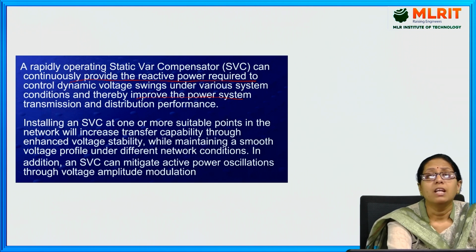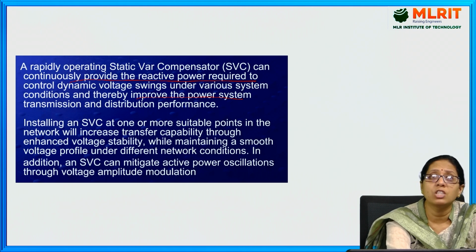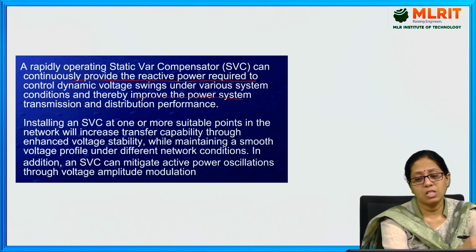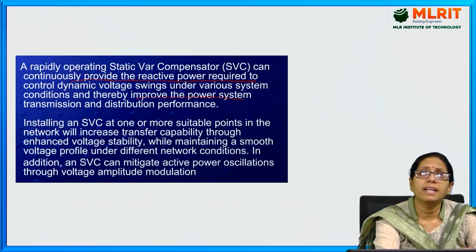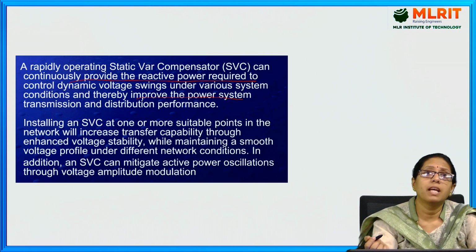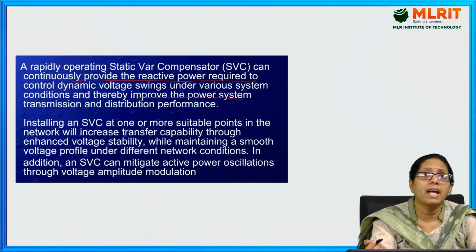That is, in order to increase the transmission as well as distribution performance or the efficiency of the whole system, we will be using this SVC technique to provide the reactive power which is being required based on the voltage swings. That means there will be voltage sag as well as swell.